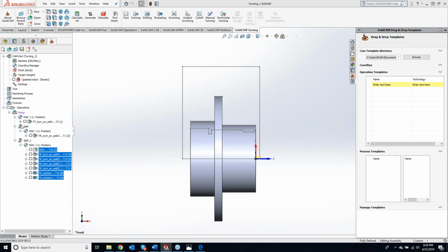So that way you guys don't have to go in there and, like I said, manually hack up the G-code file. This is a much safer way just because all the cancellation lines are in there, the retracts are all at the right spot. So great thing to have right there.